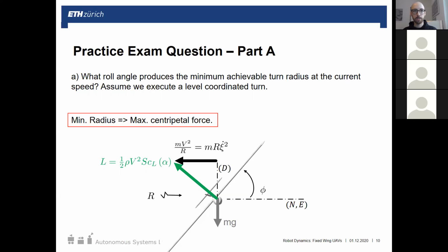Again, to make sure it's clear: in 2D airfoil analysis we're only looking at the airfoil, so angle of attack is from flow to chord line, but for the full aircraft, it's from flow to body axis. Okay, next question.